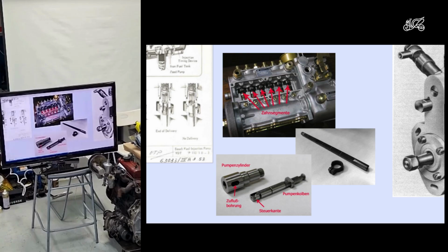And as you open the throttle, the air comes in more easily. The pressure in the manifold rises. So manifold pressure is a key signal of how much air is coming into the engine. And that's actually how modern injection systems work. All modern injection systems have got a manifold pressure sensor.